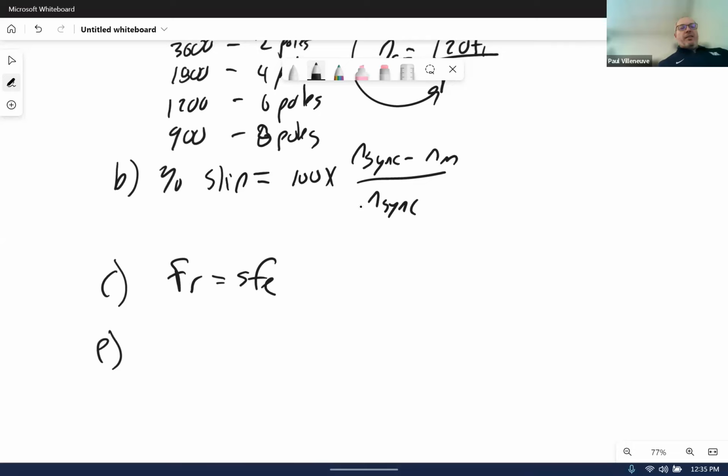Spin at synchronous speed. It has to spin at synchronous speed because our induction motor wants to output constant torque. And since the AC field, or the stator field, as a result of the AC current flow, is at synchronous speed, for those two to maintain a constant torque, they have to spin at the exact same rate. And if you also recall, the reason why you get a rotor field that is spinning at the synchronous speed is because on the rotor itself, you have an AC waveform.